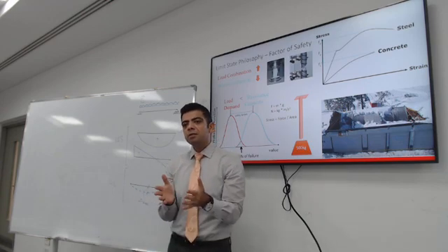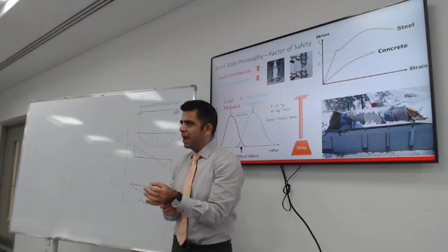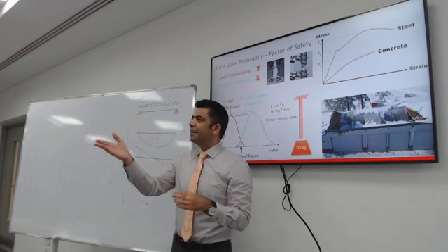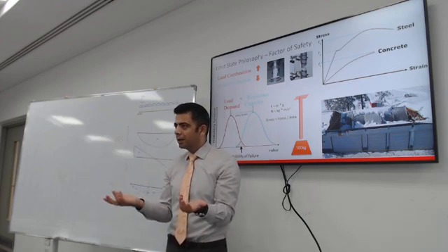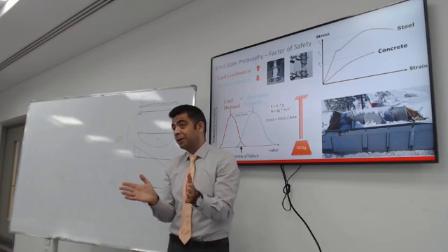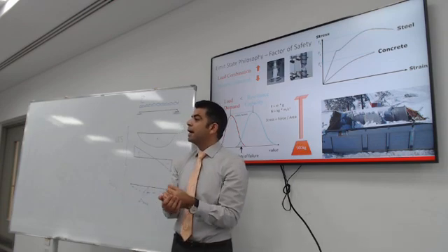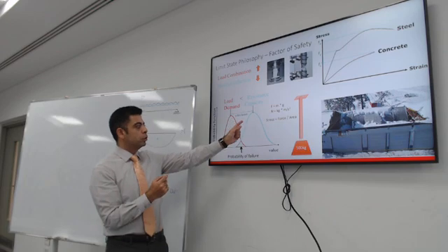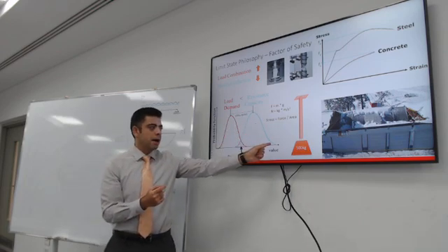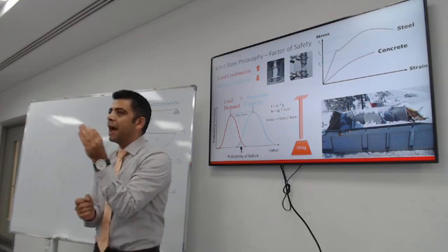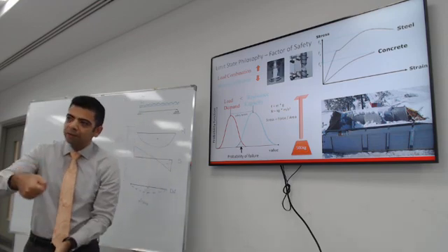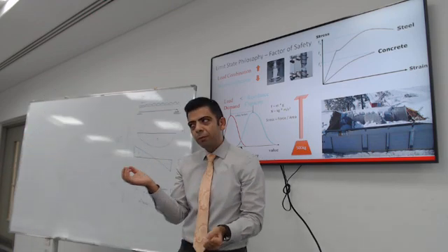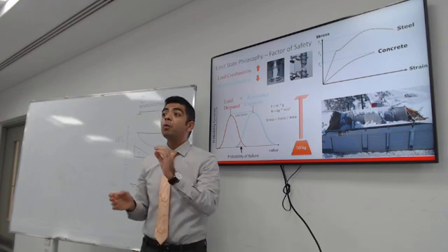Okay, so how much is too much snow? Do you know exactly the amount of snow that will fall on this house this winter? There is a probability. You could have a terrible winter and the snow is huge, or you might not get snow at all. So this introduces that the load is a probability function. We're not 100% certain of the exact weight of snow that will fall on the building. Same thing with wind. We're not sure exactly what the wind speed will be every day, but we can guess.